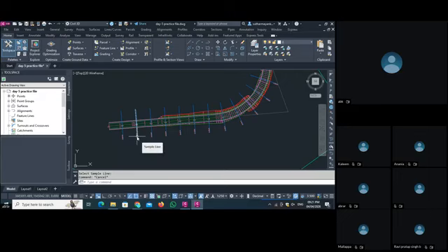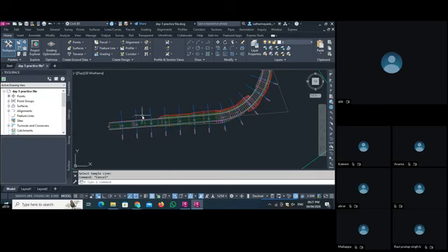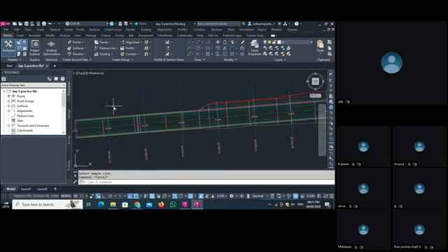So this is the most important thing for the site engineers. You have to give this cross section to the site engineers, so based on this cross section, they are working on the site. Okay, so first of all, you have to create a section view. Then you have to create sample lines, and then they display these things.